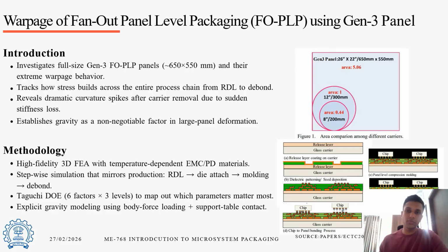One specific thing only this study has considered is gravity. It has explicitly modeled the gravity using body force loading and support table contact. When the panel becomes thinner and thinner, and especially after the carrier is removed, gravity plays a very important role in the final warpage of the panel.